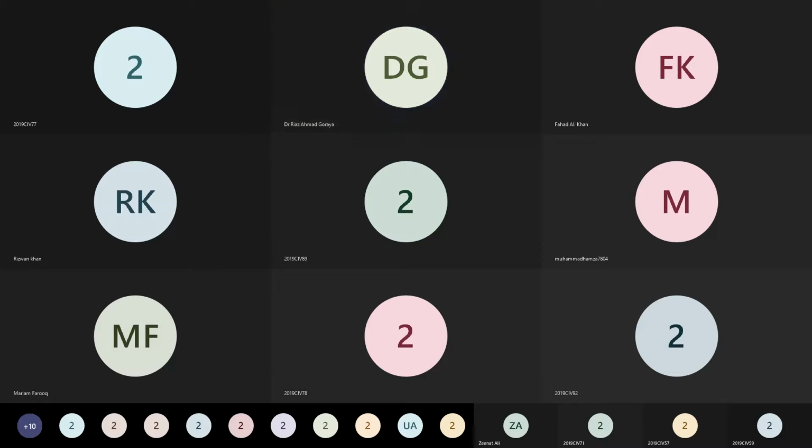So the main difference between the method of joints and the method of sections is, one, that the method of joints is applied and preferable where the complete analysis of the truss is required. Whereas whenever there is a situation where you want to determine the member forces for selected truss members, then you should prefer the method of sections, which we will study today.